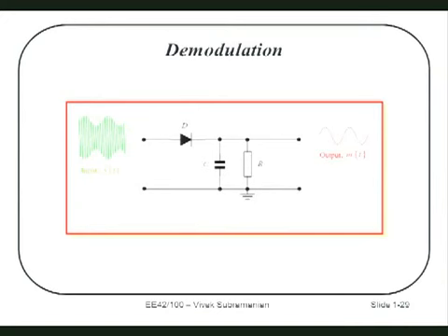That's conceptually the idea, and we'll talk more about that when we talk about impedance. So that's the basic idea. You can actually buy these at Radio Shack. They're called crystal radios or batteryless radios, and they work reasonably well. It's basically a coil, a tuning capacitor to set the frequency, a diode, and a high impedance headphone. No battery, and you can listen to AM radio.